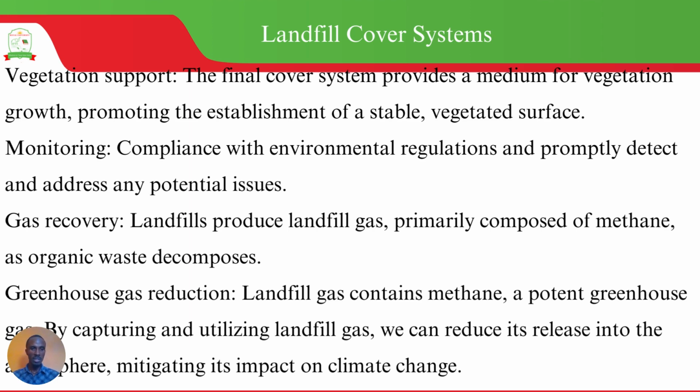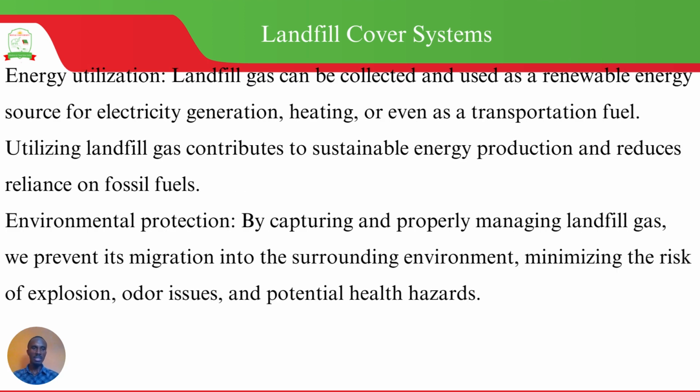Then gas recovery, as we said, landfills produce landfill gas, which is primarily composed of methane as the waste, which is organic, decomposes. So we also have greenhouse gas reduction. This landfill gas that contains methane, which is a potent greenhouse gas, will be captured and utilized so that we reduce its release to the atmosphere and mitigate its impact on climate change.